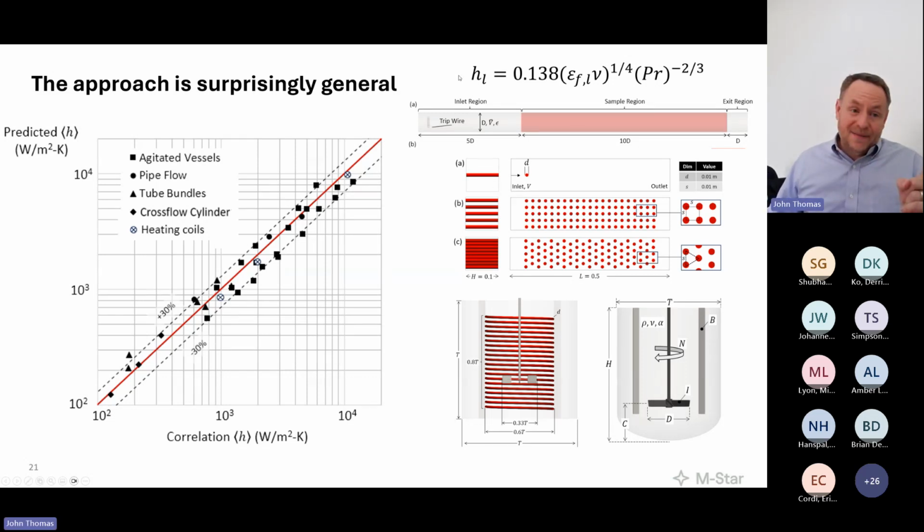In the simulation, I have one to rule them all. One that's appealing to local turbulent physics, as it were. One that's describing local convection as a function of local fluid properties, EDR, and other thermophysical properties, specifically viscosity and thermal diffusivity. And the mapping between the two, regardless of topology, is consistently within 30%. And that's not bad considering the correlation uncertainties are typically 20 to 30% on a good day. So the fact that we can reproduce this across 2 orders of magnitude of H is pretty cool and speaks to the generality of this turbulence theory.